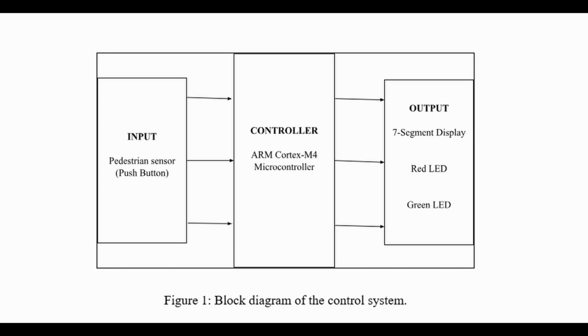In the center is the controller, the ARM Cortex-M4. It processes the input and controls the timing logic. On the right are the outputs. We have a 7-segment display to show the countdown timer, and also two LEDs, red and green, to act as the traffic signals.